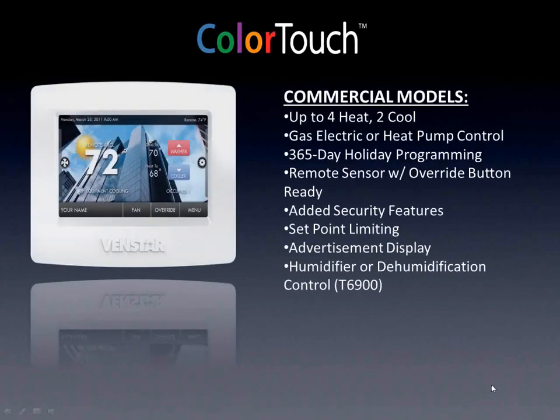The commercial versions of the stat are very similar from a functionality standpoint, same kind of thing, 4 heat, 2 cool, or 3 heat, 2 cool for a gas system. It also has 365-day holiday programming, so if you're doing a commercial building with the stat and they have whatever 10 holidays a year, at the beginning of the year you can punch all the holidays in, and then you're automatically saving energy during those time frames.